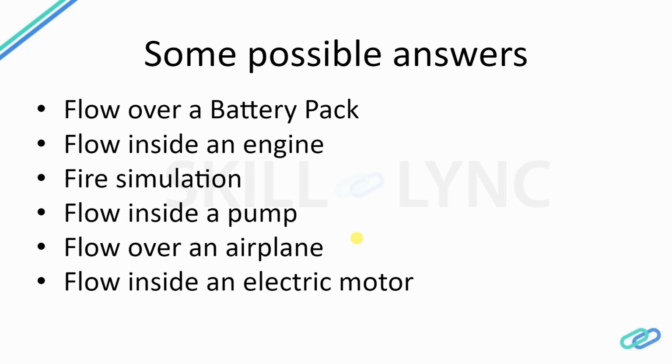It turns out that anywhere fluid actually flows, you can use CFD to optimize the system if you really care about the system. In the context of electric vehicles, you might be interested in simulating the flow over the battery pack to make sure that the batteries are cooled efficiently. In the context of IC engines, you might want to see how the air actually flows through the intake port of an internal combustion engine and calculate things like volumetric efficiency. In the context of safety related simulation, you can simulate how fire spreads in a room, and the examples can keep on going.